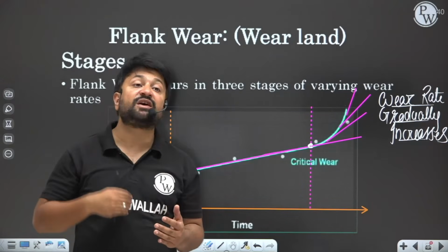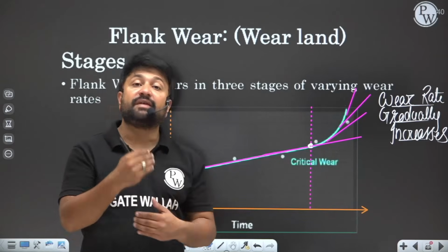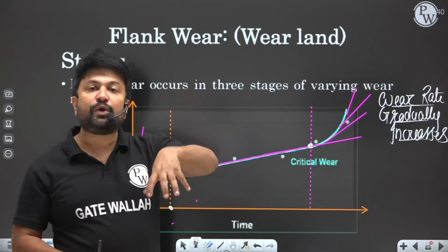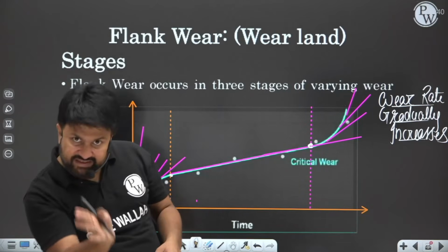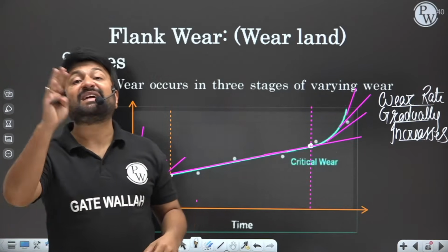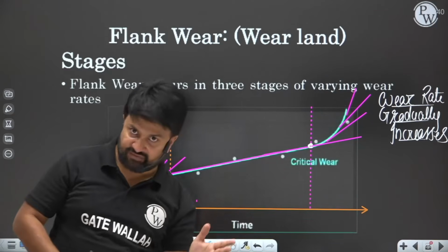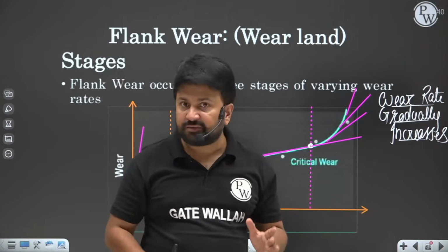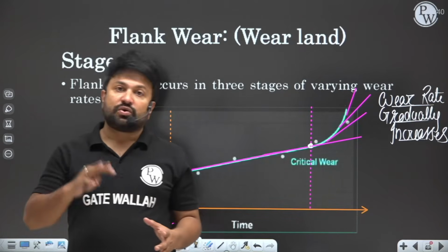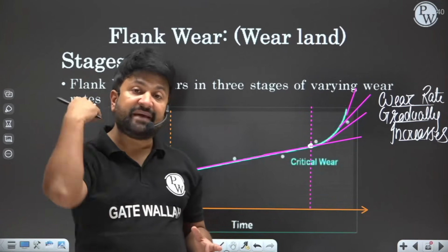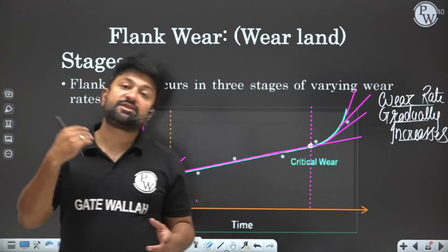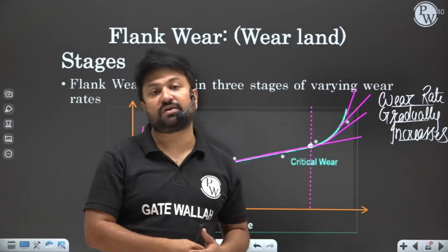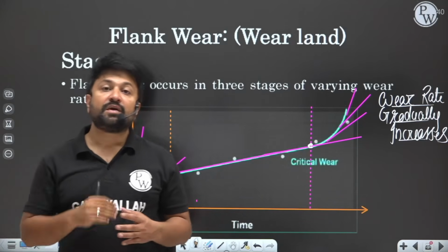And if the built up edge forms, then built up edge is regularly sheared off, and it will do a plugging on the flank surface, okay, whether it is a side flank or an end flank, right? And generally side flank comes in contact with the workpiece. So that side flank basically spoils the surface finish of the workpiece, right?